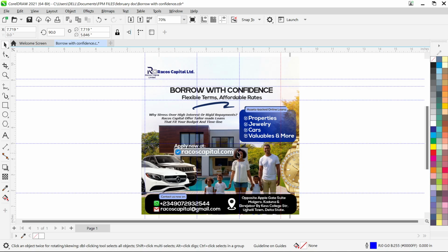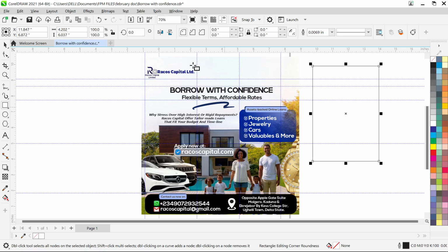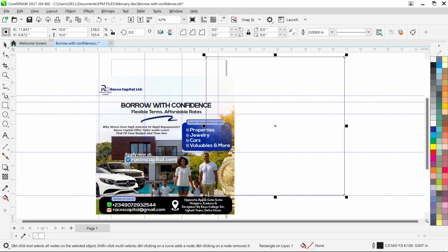Without skipping, as you get it without skipping. Now, firstly, I always tell you anything you are doing is inside a shape. How to get this is F6, that's this function key, but I'm just going to click it here. You can see my cursor. Just draw any shape I want to draw, then come over here, highlight and write 10. I'm using 10 by 10 inch. Type 10, 10, then click enter. F4, Control space, that's for you to move this. I want to make it straight.